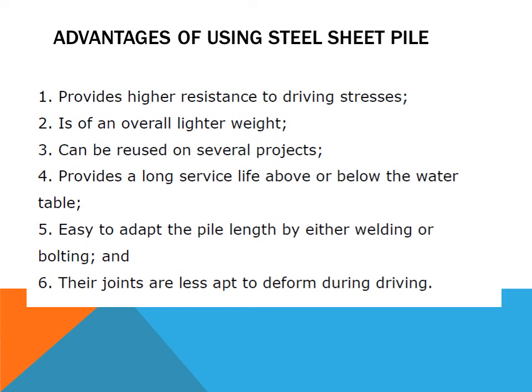Okay, why should we use the steel sheet pile instead of other materials? First, it can provide higher resistance to driving stresses. Second, it is overall lighter in weight, and it can be reused on several projects. It means that after the excavation, we can withdraw the steel sheet pile and use it for other projects.